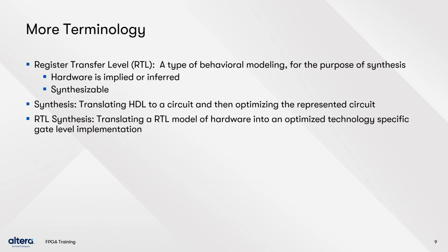RTL stands for Register Transfer Level. It's a common term that describes a style of behavioral modeling that defines input-output relationships in terms of data flow operations inside your hardware model. RTL constructs are synthesizable. Synthesis refers to both the translation and optimization of HDL code into a circuit of a particular technology, for example, lookup tables and flip-flops of FPGAs. RTL synthesis simply refers to the translation of an RTL model.